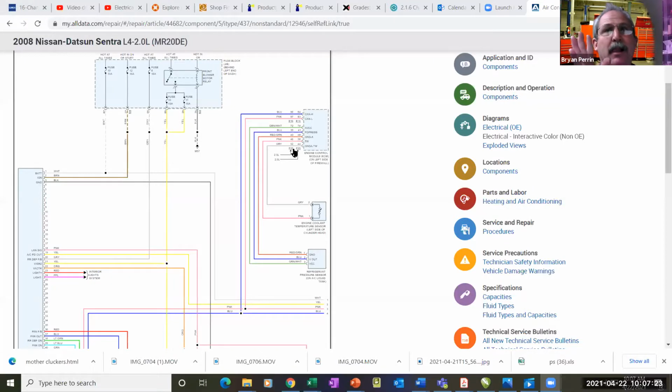May or may not. But I do know you have the generic scan tool. So the next step is go into the engine module. Does it see that you're asking the AC to be turned on? And you should have a PID, obviously for engine coolant temperature sensor, but also for your AC pressure sensor. Those should hopefully both be supported in generic. If they are, then you can see, do I have pressure? Because obviously if there's no pressure, we're not turning the thing on. And then you can also see, is this requesting the intelligent power distribution module to turn it on?